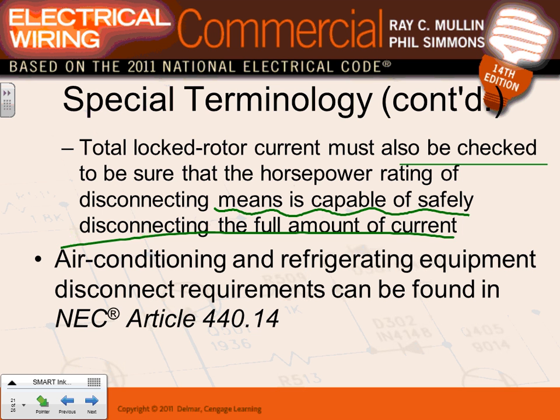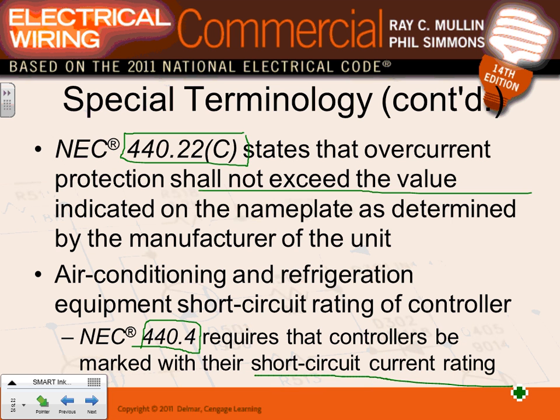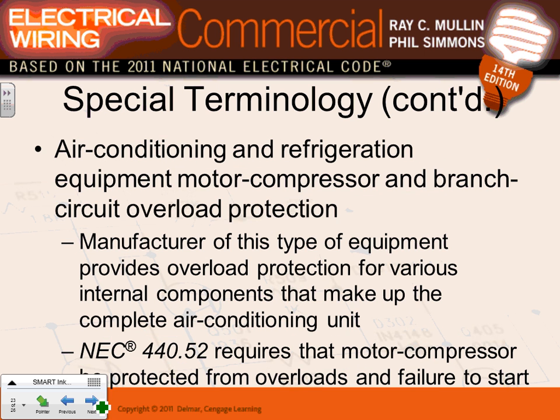So that's your equipment here. The overcurrent protection device must not exceed the value indicated on the nameplate. This is the most important thing for the overcurrent protection device, the maximum overcurrent protection device. This article does require the controller to be rated to handle the short circuit withstand rating. If I have a controller, I need it to be able to withstand the short circuit. That's what it tells you. You don't want it to explode in your face if there's a short circuit.